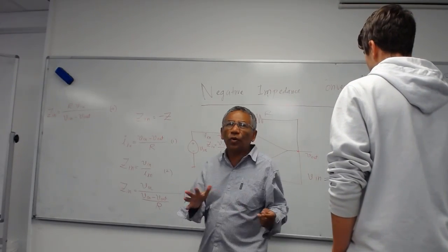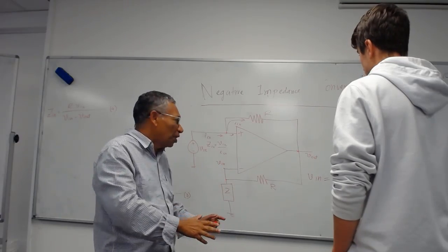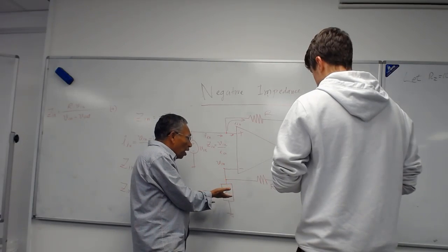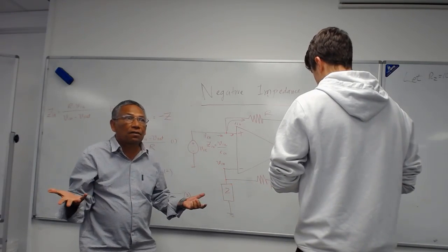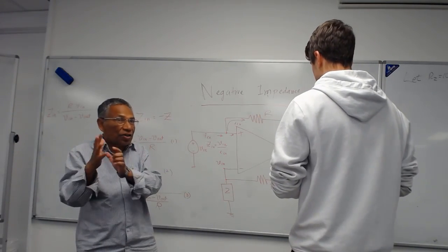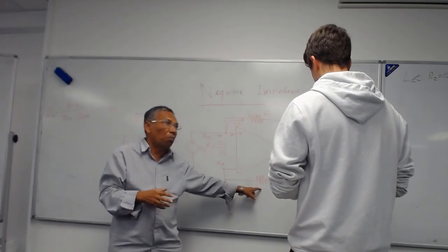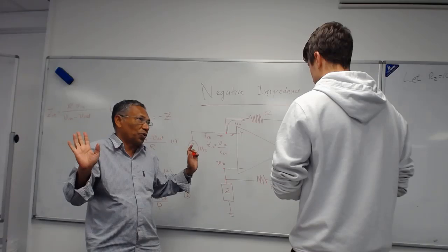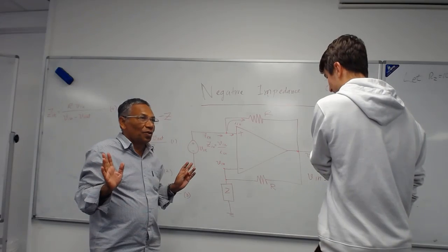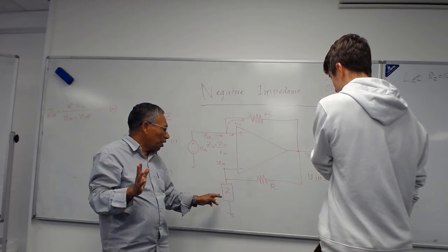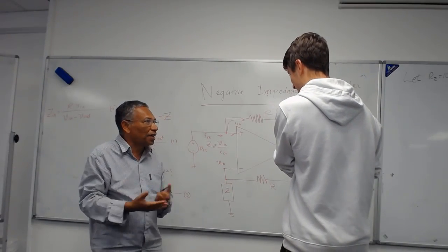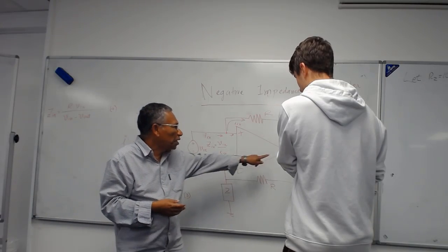It's very easy. You see, what you did before is just an extension of that knowledge. You had R1 and R2, remember? And you did a voltage divider. This is the same voltage divider where you have R and another one is a Z. Both are ohms. You see, Z is the impedance which is complex. It has got an R and an L or a C. But this is also ohm, this is also ohm. It doesn't do anything. It doesn't bite you. These are harmless creatures. So the way you treated R1 and R2, you can treat Z as R2 and R1. And just write the voltage divider equation. So V in is the voltage division of V out by R and Z.